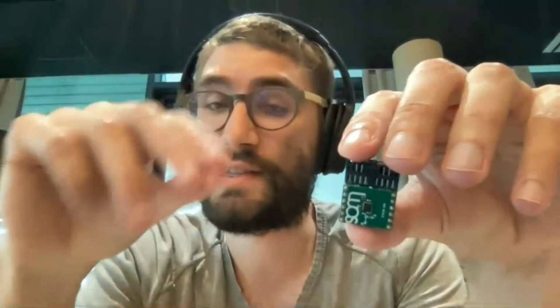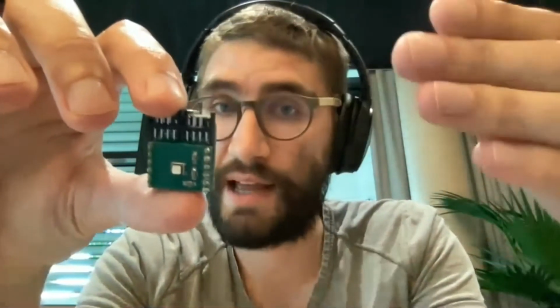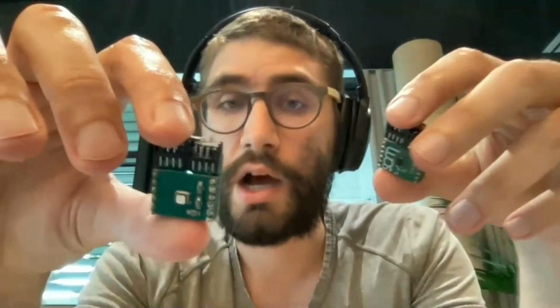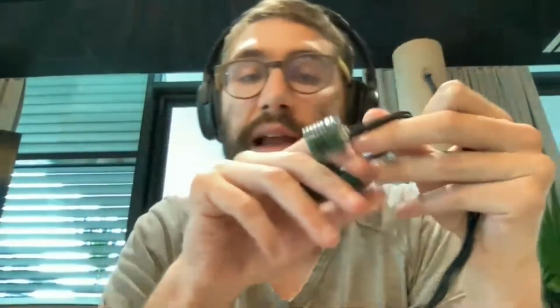So on this one, there is one service, which is a driver, allowing me to access the motion sensor. This service will be declared in the system, and anyone can use this sensor. On this board, which has an RGB LED, I put 2 services. One is a driver allowing me to access this RGB LED, and another is an application one, allowing me to get the value of this service here and to make the LED blink when there is a movement. To make it work, I just connect those 2 boards together, and I'm going to use a power plug to emulate the battery of the bike.